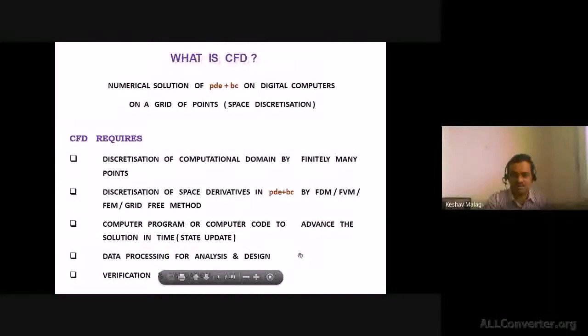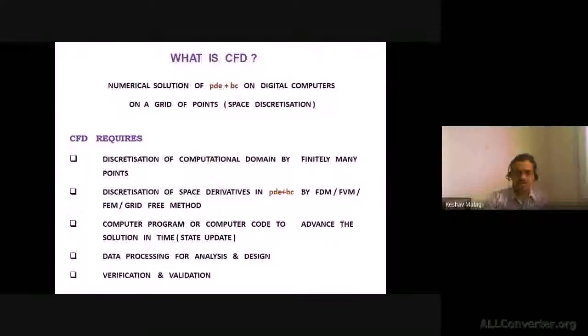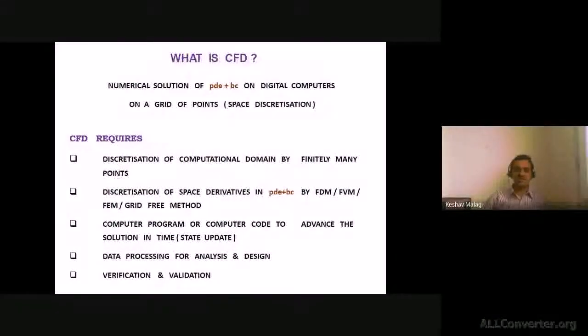So what is verification and validation? In a nutshell, you will write a code and generate a result. You need to know two things very essentially. One is the verification aspect, which involves whether I am solving correctly. You have chosen a mathematical model, you have written the code, and you are solving. So the question you ask is whether the code I have written, the numerical method I have coded, is right. Is it functioning correctly? That is called verification, whether what I am solving is correct.